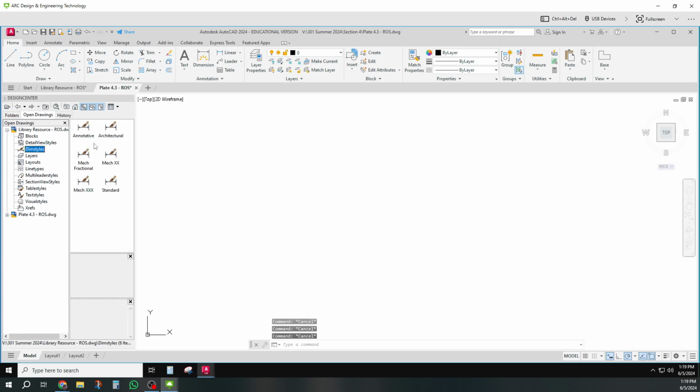I'm going to go ahead now and put my dim styles in too. It's going to be an architectural dim style. And I'll put my text styles in, architectural. And I think I'm going to use the landscape leader style when I have leaders to write. Okay, so I think I've done a lot of extra up front. I've got a lot of stuff set up. Let's go to the thick layer.